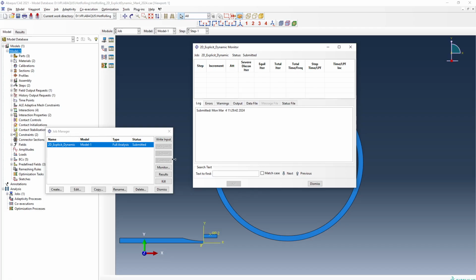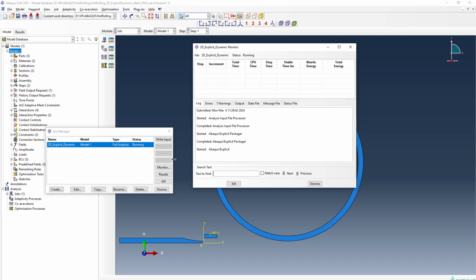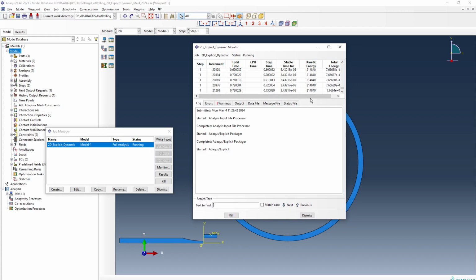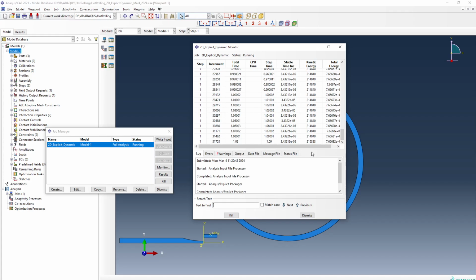So for the analysis to progress, the nodes must have displacement and temperature degrees of freedom. For the descaler, the default element type was a plane strain element, so there was no temperature degree of freedom, so it gave an error. So the analysis is progressing well. We'll wait until it is done before we go and start doing some post-processing analysis.